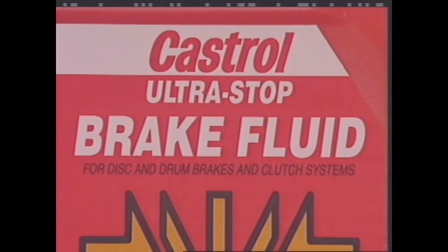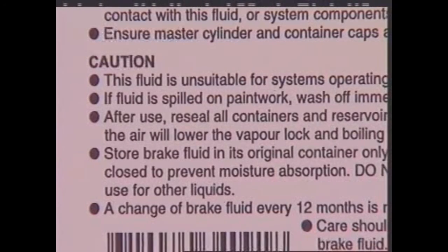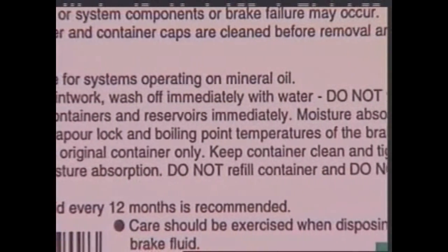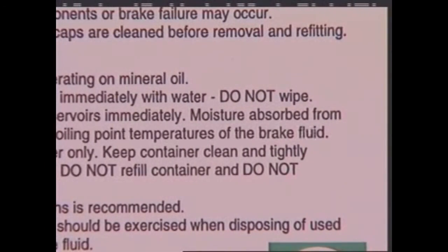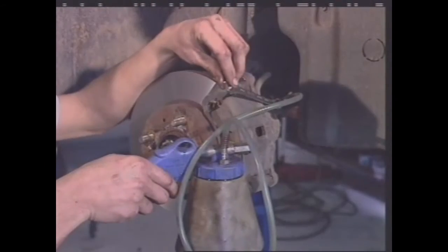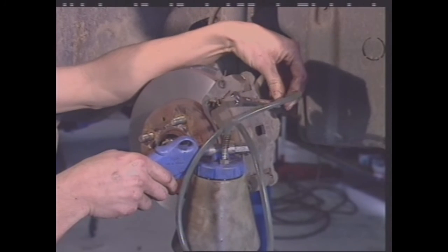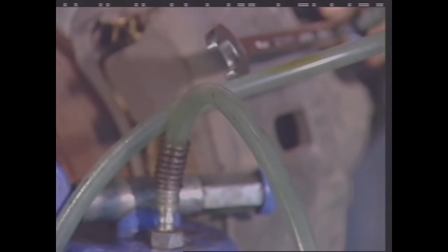Glycol-based fluids meet most requirements, although they do damage paint. And they absorb moisture, hence the warnings. This is important because as moisture is absorbed, it lowers the boiling point of the fluid. Brake fluid should not be mixed with mineral-based oils or solvents. If contamination is suspected, the braking system must be drained and flushed with a suitable solvent and rubber components replaced.